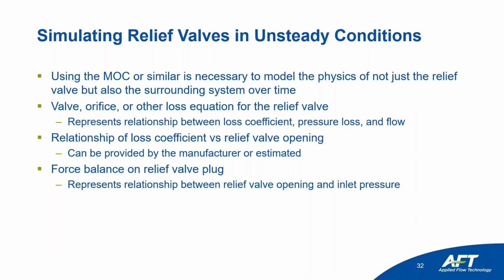For more intense modeling, you would find it more in higher dimensional software or possibly in vibration analysis. You might be interested in a force balance on the plug itself. And usually you would just try to find some way to tie it between the relief valve opening and the inlet pressure. As long as you could do that, you could still technically use it in a one-dimensional simulation, but a lot of times it's overkill for what we're looking for in a systems analysis.